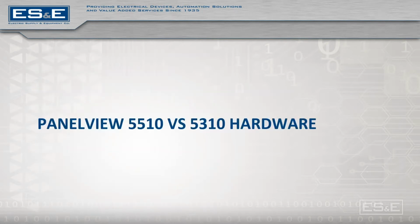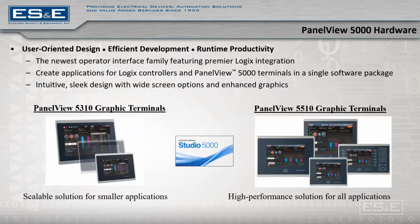So to start, we're going to work with the PanelView 5510 and 5310 hardware. The PanelView 5000 came out to allow a single source platform using Studio 5000 for both the HMI as well as the Logix controller. With that, you must use a Logix controller, CompactLogix or ControlLogix, in conjunction with the PanelView 5000 hardware. But the new hardware is a lot more intuitive, sleek, and enhanced in comparison to our PanelView Plus partner.